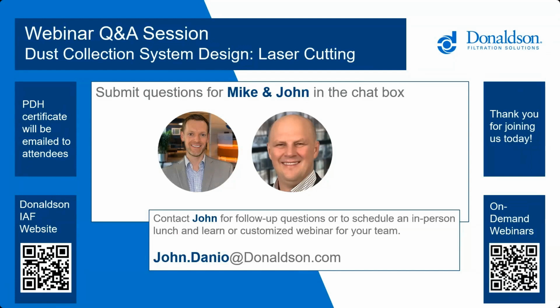Thank you. All right, next question is related to AMR. What AMR is recommended for laser cutting applications? Yeah, so typically when we're looking at fiber laser, it can really range. Everyone does it a little bit different, but we typically try to look at about a 1.5 to 1. Could be 1 to 1. It just kind of depends on the table itself, and the power of the laser is also an important factor in looking at AMR.